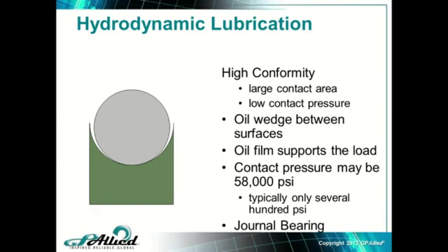So what happens then is, as the lubricant molecule is riding on the shaft, and as it goes into the load zone, and if you can see my mouse there, let's say rotation is this way, so the load zone is right in here, right? As it goes into the load zone, pressure starts to build on the hydrocarbon molecule. The hydrocarbon molecule resists compression, and it actually pushes back, and it's able to push back really hard. So as that molecule rolls into the load zone, an oil wedge is formed. Now, this oil wedge is harder than the steel, and it keeps the steel shaft and whatever the journal bearing's made of separate, doesn't let them touch.